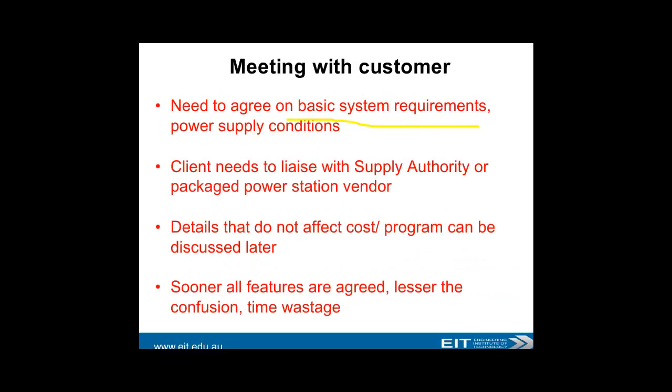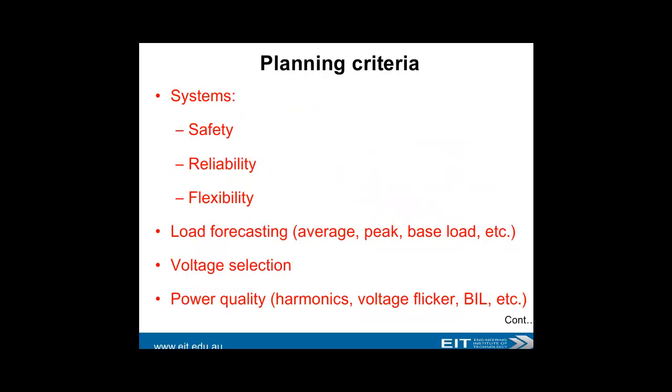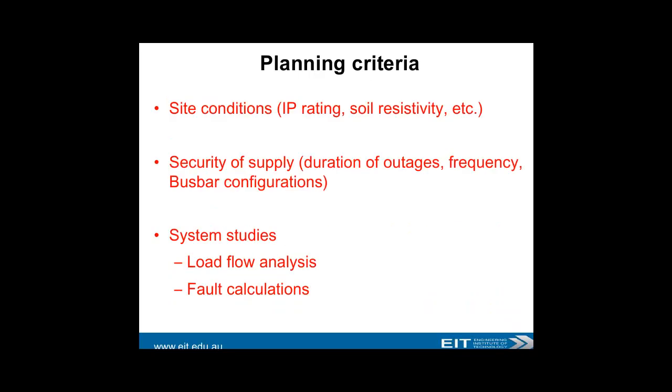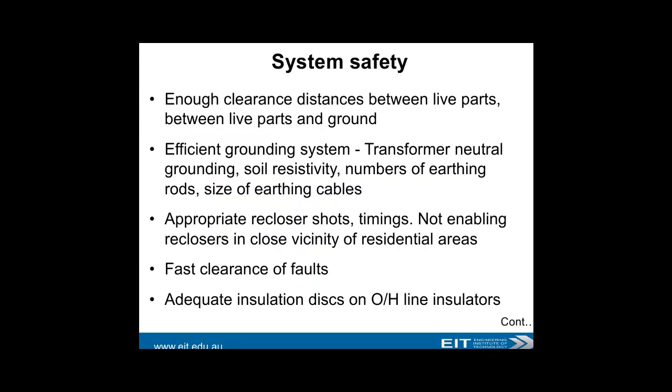Agree on basic system requirements, get the supply authority involved, and obviously try and avoid cost or time scheduling blowouts. The sooner you agree, the better, with minimal time wastage. So planning criteria relate to safety, which is obviously critical, reliability and flexibility. Load forecasting, very important, voltage selection, power quality. Site conditions, very important. Security of supply and system studies, load flow analysis, fault calculations.